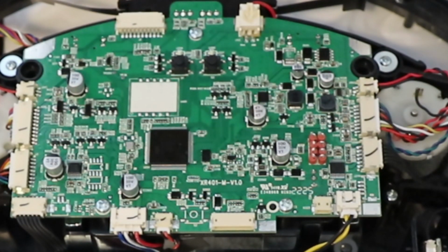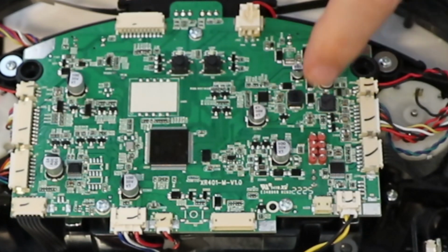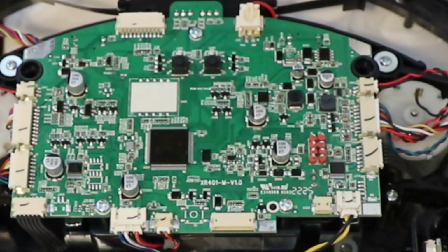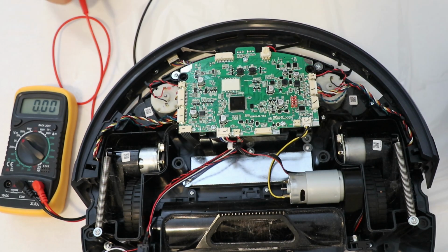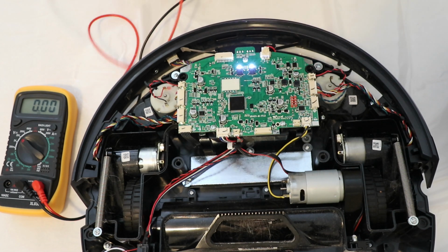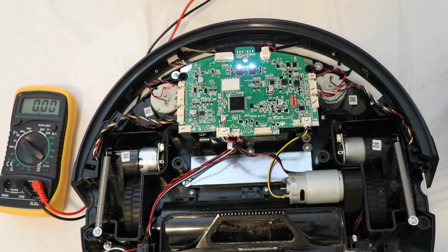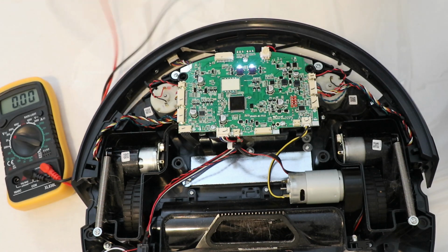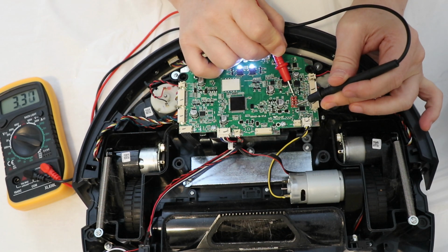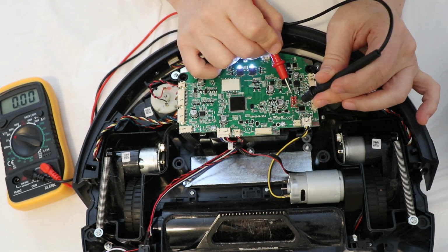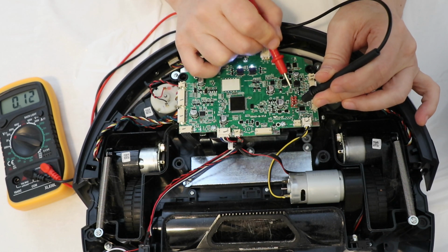And just looking at the PCB up close, I bet the middle two are transmit and receive, and these two here are power, 3.3 volts. But let me put the battery back in and we'll measure some voltages. Okay, the battery is back in the device. Let's power it on. Okay, we see signs of life. Now we know the top one is ground, so I bet this one is going to be 3.3 volts. Yep. And I bet this one's, oh, that one's, yep, 3.3 volts.